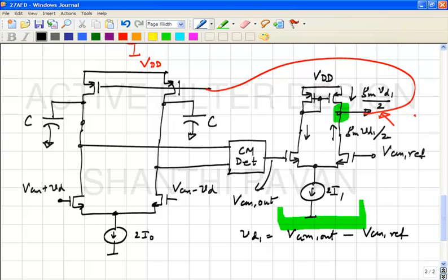Okay, so we need to bring in not only all the intentional capacitors that we put in, but also a whole bunch of parasitic capacitances that occur due to device parasitics. We know that the MOS transistor has input and output capacitances and so on. All these things affect the phase margin and stability.